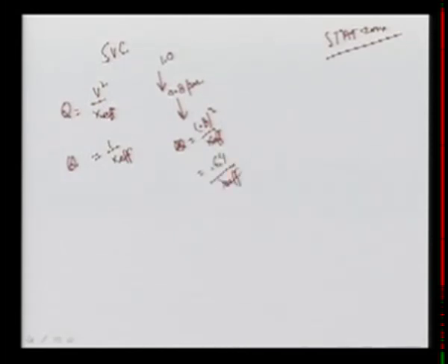What does it mean? Now when the voltage is less, the reactive power provided by this system is less. It means that when we need more reactive power, it is providing less. Here it is providing more, it is 1 per unit. So therefore here you can say the reactive power reduction is the square term, and therefore when we need more, it provides less. So this is not so superior.